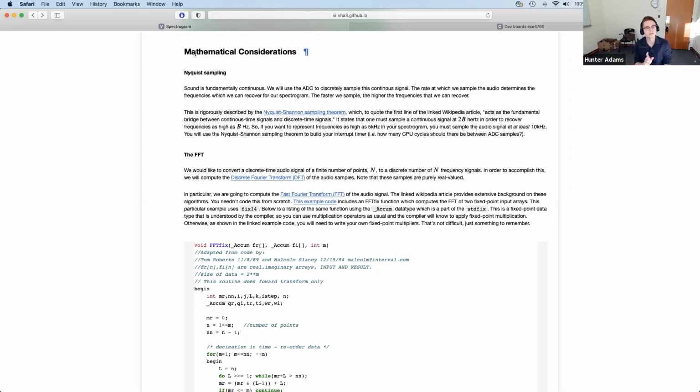So when you slide that slider, what's going to happen in your code is you will have to disable interrupts, turn off the timer, reconfigure the timer to a new overflow value that is whatever value is necessary to interrupt at the speed needed to make that range adjustment, and then re-enable interrupts.